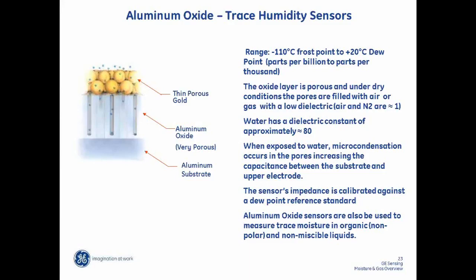It has a dielectric constant of about 80, and gases such as nitrogen or air have a dielectric of about 1. So essentially you can think of this as changing capacitance. Each pore acts as a parallel capacitor, and when capacitors are placed in parallel, you add them together. So essentially this functions as a water molecule counter. And as it absorbs more and more water, the capacitance increases.